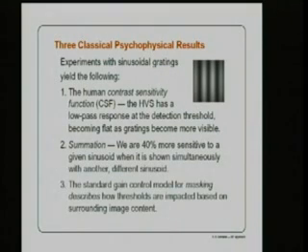Masking is the concept that if you look down at the carpet in here, it's quite detailed. So if we put some white noise on top of the carpet, we would say that the carpet texture hides the white noise, right? You wouldn't be able to see the white noise until there was a lot more of it, as opposed to showing you white noise on a flat background. So the idea of masking is other image content can hide whatever your particular target is. Standard masking experiments are also done with sinusoids and white noise, but the idea is that the image content influences how easy it is for you to see some particular component.